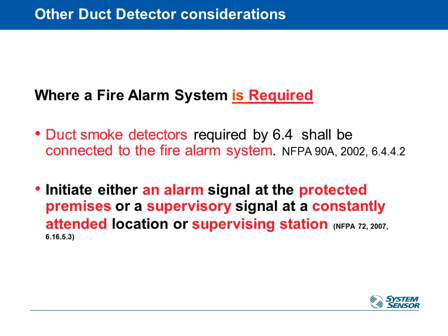On the flip side, if I am putting a duct smoke detector in a building that does have a fire alarm system required by NFPA, then I do have to connect that duct smoke detector to the fire alarm system. There are numerous ways to do that. The most common is through the trouble contacts circuit, so that when one of the smoke detectors trips, the fire alarm panel is notified of that.